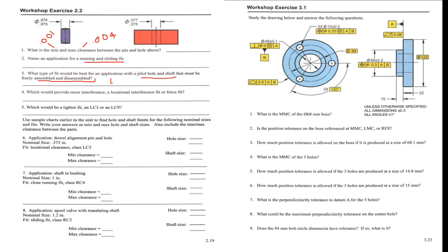A locational clearance fit we can use here. Locational clearance fit. Well, a force fit will provide some more interference, and a tighter fit, LC3.